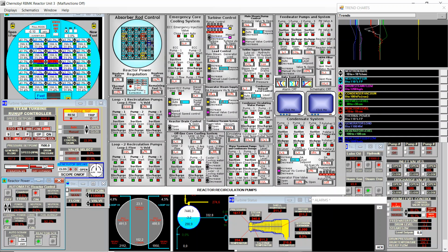Okay, and everything looks fine to me. We should keep an eye on the turbine temperature of the rotor and the shell. We don't want to get too high a differential between the two. I will continue powering down by decreasing power set point. Now let's go to 20.